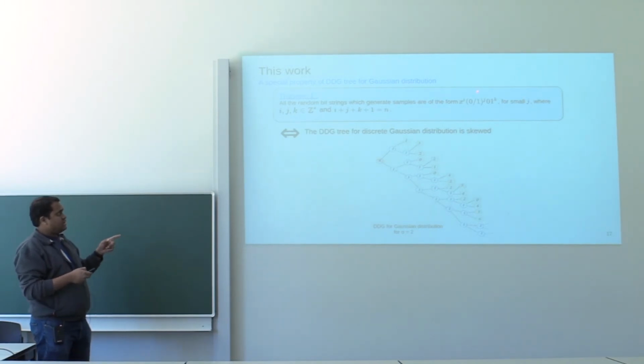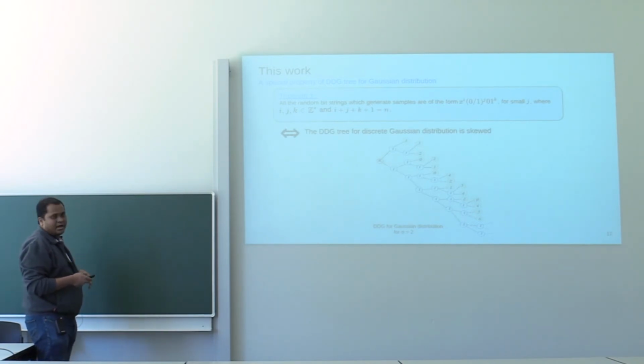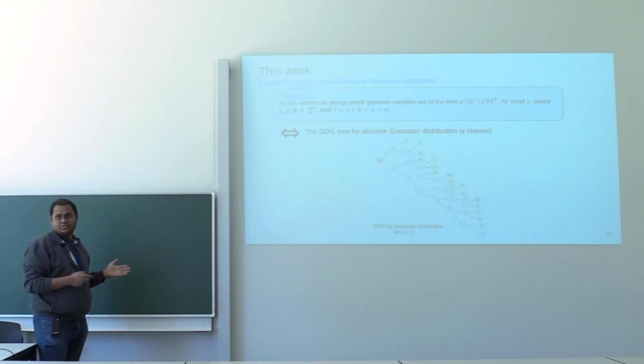The important thing is that this variable, binary bits j, has to be very small. I mean, usually less than 5 in most cases. Otherwise this tree is not skewed. So using this theorem, I can show that I can devise a very good divide and conquer strategy to minimize my Boolean expressions.